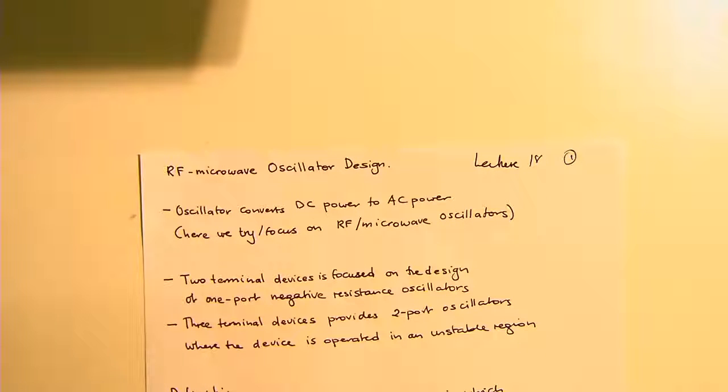Okay. In the simplest of forms, but it's not how it works in practice. When you're doing your advanced comms, usually what they assume is this mixer is actually a multiplication. So you go sine omega 1t multiplied by sine omega 2t.